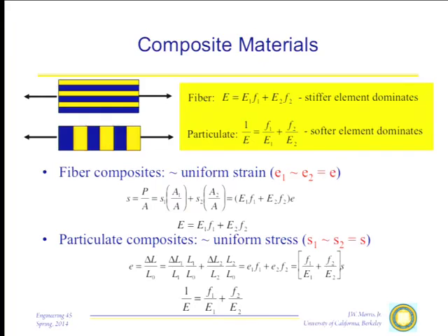unidirectional composite is. The kind of run-of-the-mill composites that we use, like fiberglass, you have an awful lot of things made out of fiberglass, and they are basically particulate composites. The modulus is good, not super, because you have to average the reciprocal modulus, but it's good enough that the stuff is worthwhile. It's very light, the modulus is reasonably high. But you don't use it for really intense structural applications, challenging structural applications. For those, you need fiber composites, and that gets you into all kinds of problems in assembly and design and so on in order to use them.